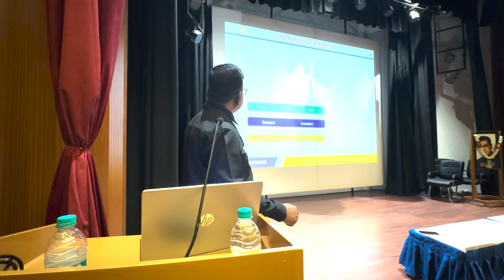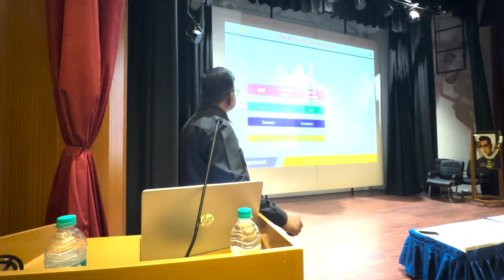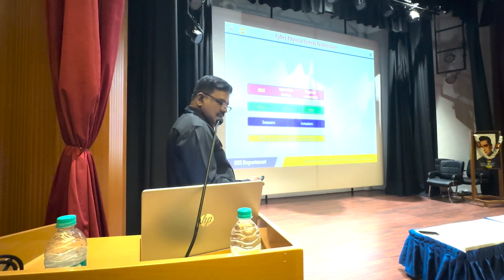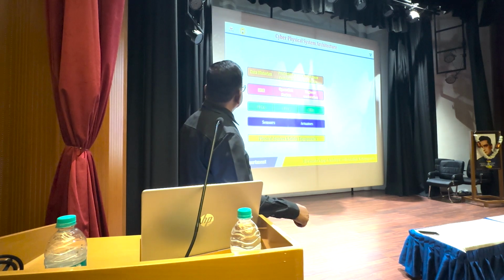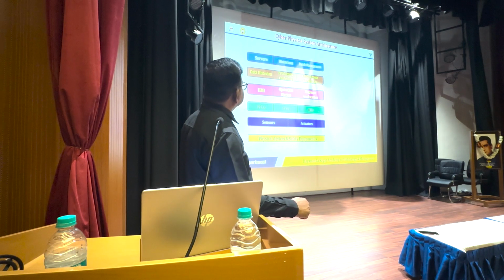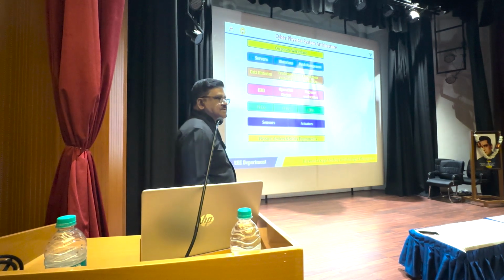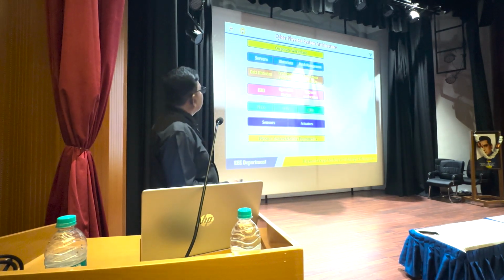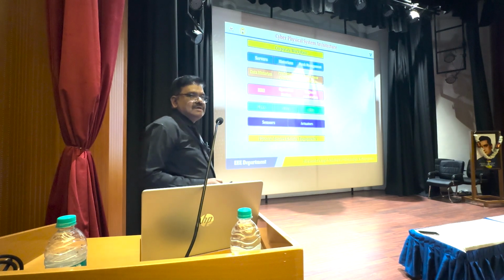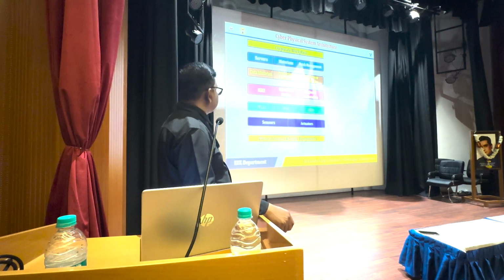IEDs will be there. Then next level we will be having HMI, operation station, then engineer workstation. Next level we will be having data historian, production controller, control room workstation. Then we will have servers, historians, patch management, the final layer, corporate workspace. So these are the 7 layers we will be having in the cyber physical system architecture.